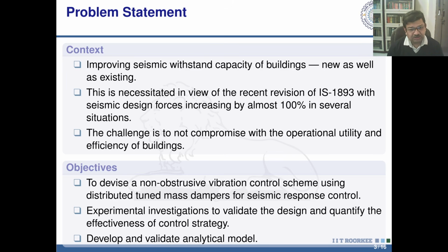non-obtrusive vibration control scheme using distributed tuned mass dampers for seismic response control. We describe experimental investigation to validate the design and to quantify the effectiveness of the control strategy. And then we also develop and validate an analytical model which can be used to investigate how much benefit this distributed tuned mass damper can provide for the design of more complex systems.